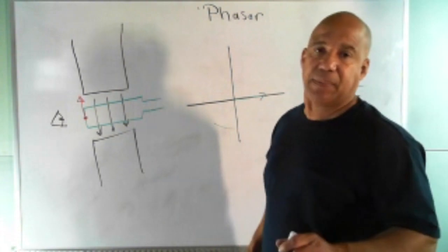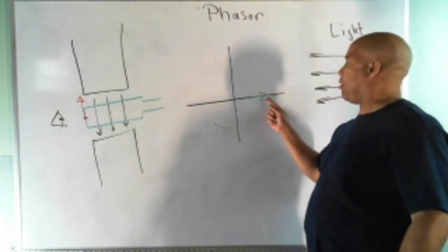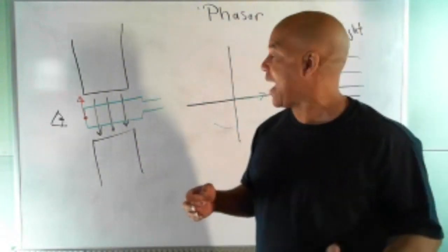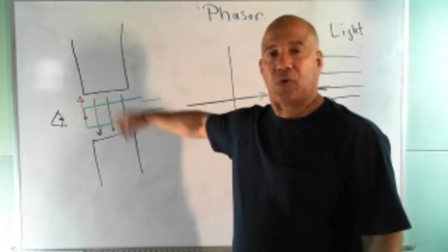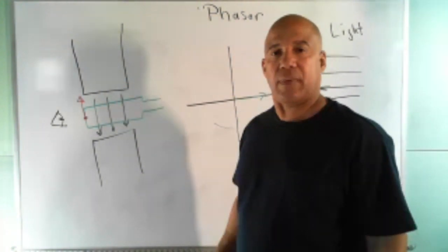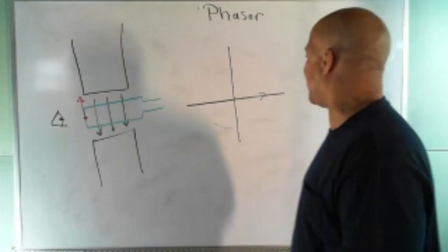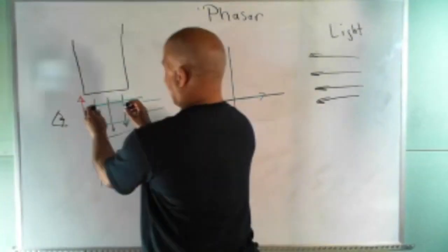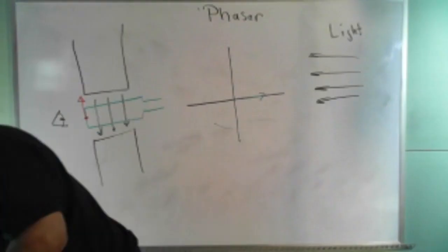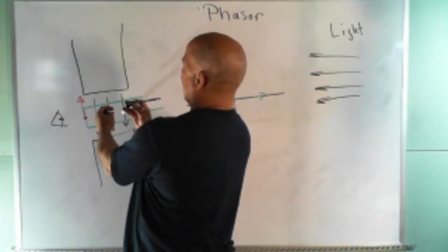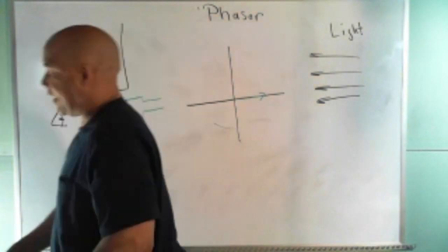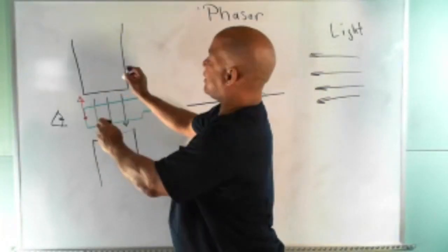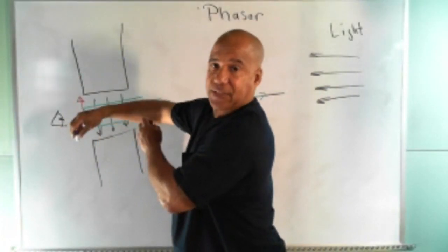But it also does something else. If we look at the shadow or the projection of that arrow on a screen, it tells us how the forces are acting as that coil moves around the 360 degrees in a circle in that generator. So when this coil is flat like that, and that phasor is off to the side, the conductors are not cutting much flux at 0 degrees. They cut more and more flux as they reach 90, and they go back to a minimum amount of flux until they go back to 0.